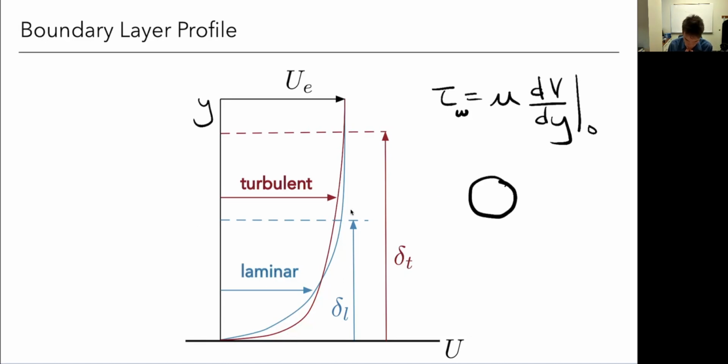As the fluid comes around, as we've discussed, we come across an adverse pressure gradient. We have a very low pressure on top and a higher pressure towards the bottom. So we're moving against the pressure, and the flow is going to want to separate, or it's going to be slowing down in that adverse pressure gradient. So particularly here in the boundary layer, it's going to be slowing down, and eventually we'll have no velocity in this streamwise direction. So it'll separate, leave the body.